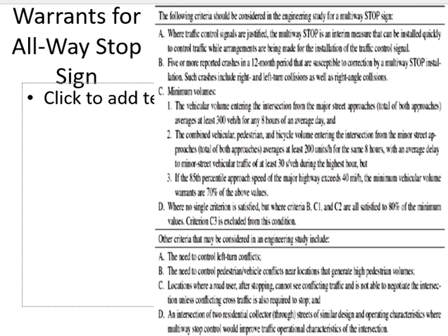Again, the crash criteria. Here they are saying 5 or more crashes in a 12-month period, for vehicles in the intersection. You need minimum volume. So the vehicular volume entering the intersection from the major street total is this or more for any 8 hours of the day. Now this will come in the signal warrants as well.